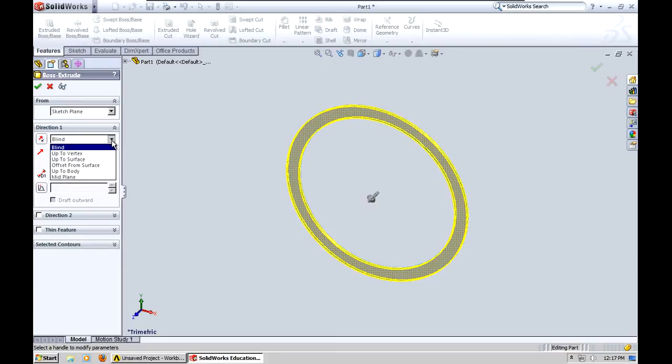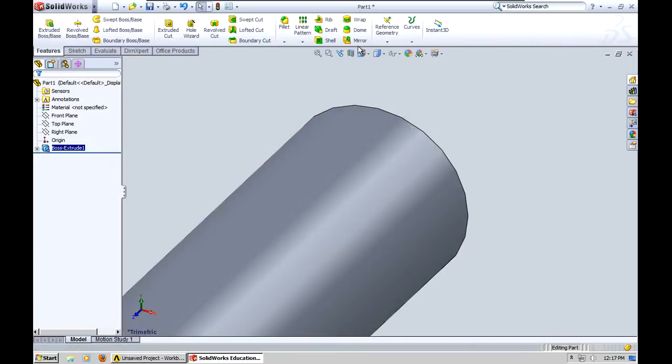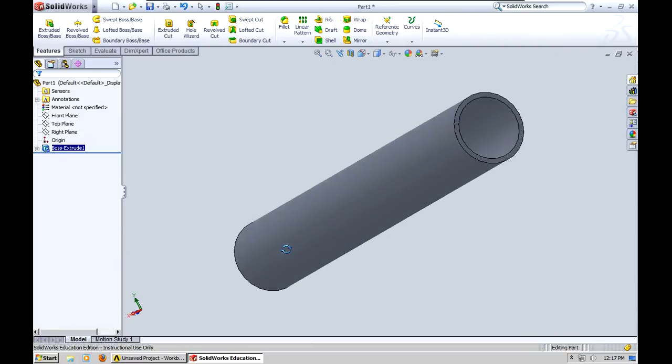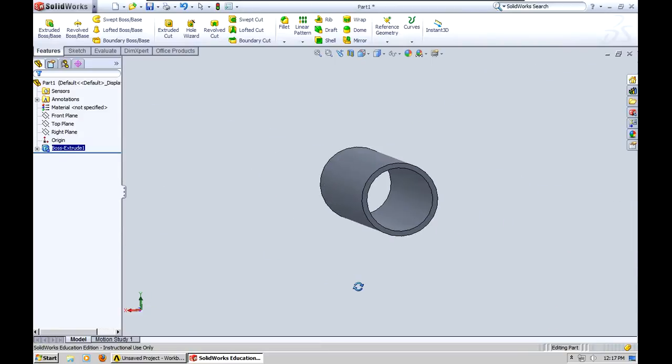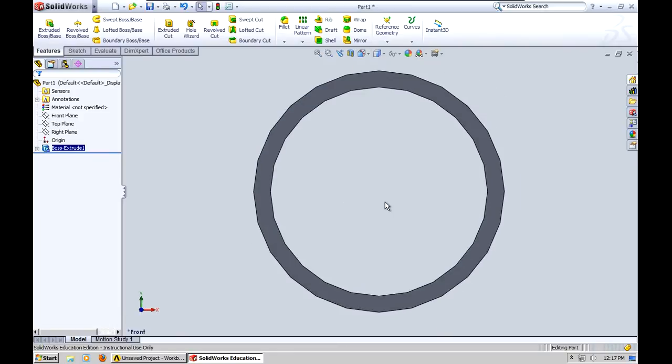I'm going to make it really large and long, and the reason is that when you start making things smaller, you have complications with the mesh, and especially with combustion, it can be a pain sometimes to get combustion simulations to work perfectly. Once you see what I'm trying to do, you'll maybe understand.